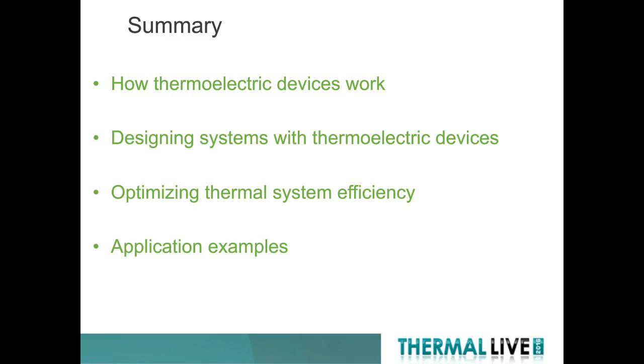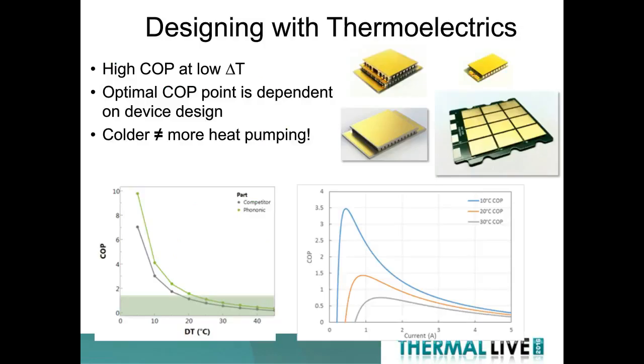We don't have to get there. We are there. But I would challenge that thermoelectrics are not as efficient as a general statement of compressors. If you look at traditional high mass volume manufactured reciprocating compressors, thermoelectrics can operate in a refrigeration system at competitive efficiencies if implemented properly, and that can be seen in our products. However, there are thermoelectric solutions that are worse. There are vapor compression solutions that are better. So it's a hard thing to wrap up. But in general, properly designed, they can be competitive with standard or average systems that are available today.